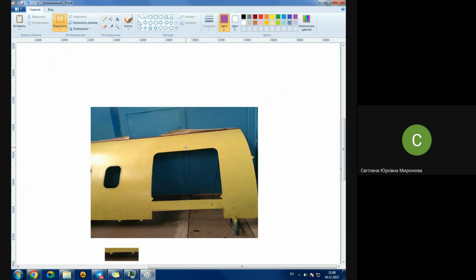One variant: such holes might be used during assembling. Not all of them at once, but they may be used during assembling as bases, so-called coordinate fixing holes or base holes. As you have no such holes, they are not permitted by the designer in the structure itself, like it might be in a rivet or in a frame. They are not given by the designer. You have no right to perforate skin in this case. That is why you may do what is called an allowance, literally put this skin.